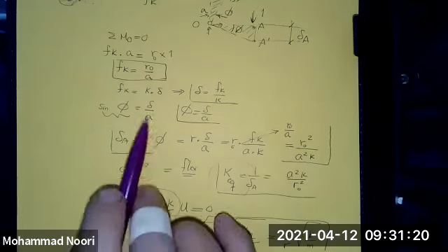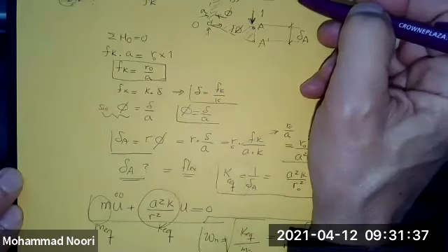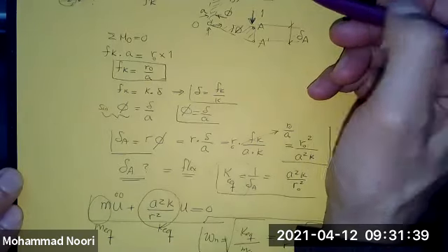Actually, quick question on the sum of the moments equation. On the left, I get why you have the spring force times A, but on the right, is that R naught times 1? Yes, because you have a force of 1 at this point. Oh, okay, we define the force as 1, because we were doing flexibility. Exactly, flexibility.